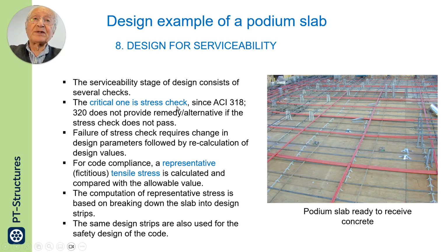The first thing I do is a stress check. ACI does not provide a remedy if the stress check is not met. Failure of stress check requires change in design parameters followed by recalculation of stress values. So I have to do stress check first.